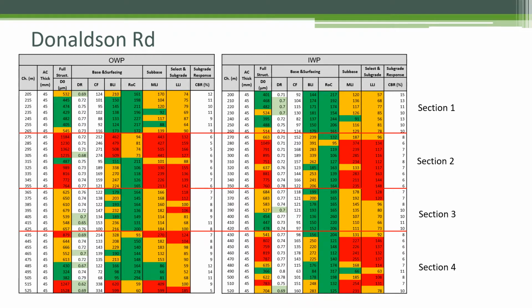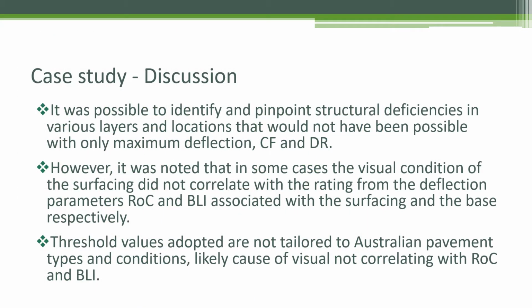So the case studies demonstrated that it is possible to pinpoint and identify structural deficiencies in various layers and locations when the additional deflection bulb parameters are adopted. This would not have been possible with only maximum deflection, the curvature function, and deflection ratio.